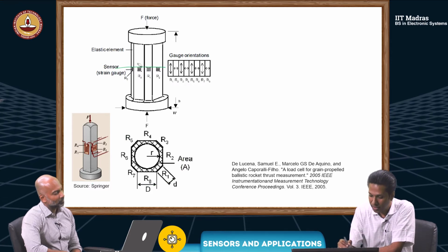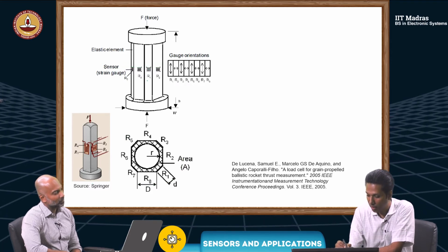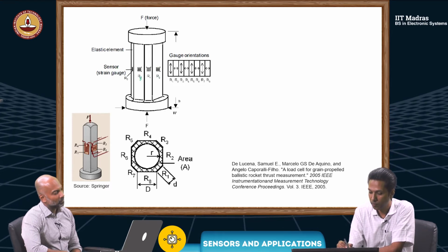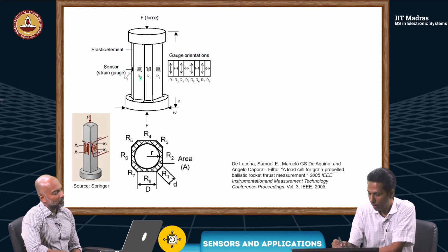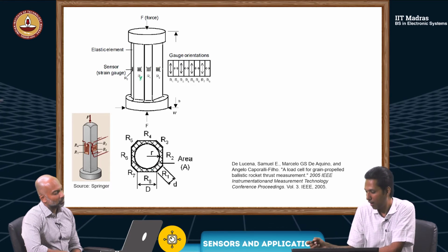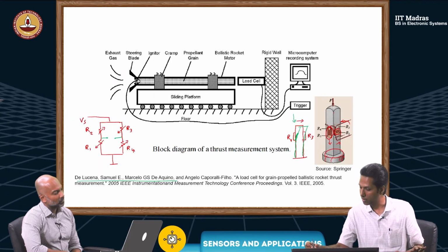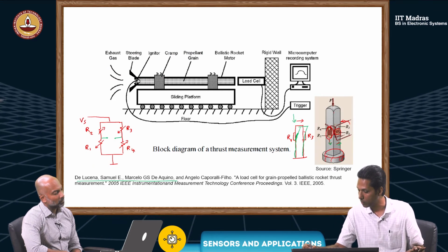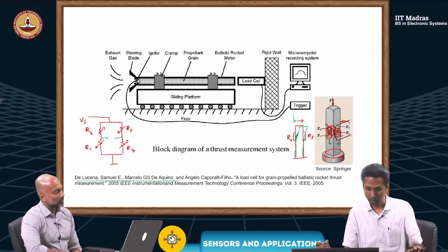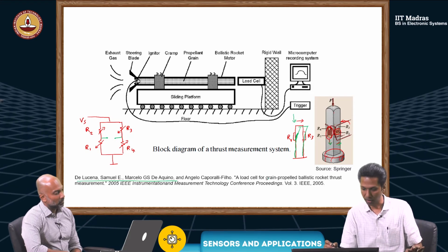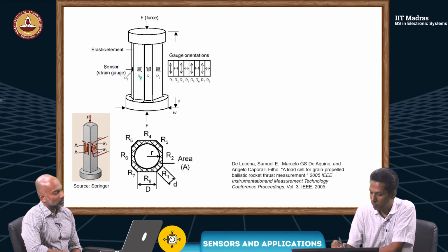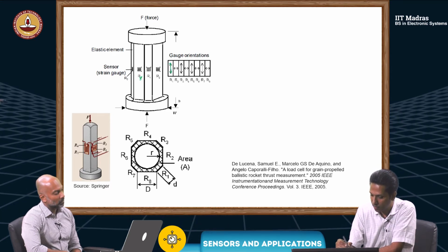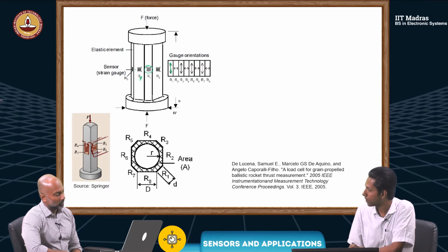And as you can see here, the sensing elements R1, R2, etc. up to 8 are arranged, as we have done in this case, this was sensitive to this direction, this was sensitive to this direction, and so on. Yes. And alternatively, it is arranged. So, in the same way here, R1 is sensitive to vertical direction, as you can see here.